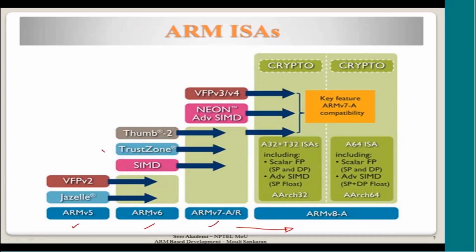Security is very important, especially in networking, and there is all the encryption and key generation, those kinds of things which are required for network protocols. There's a lot of support from the ARM processor with a separate module for it, and then Thumb-2 is an additional add-on to the Thumb state, where not only 16-bit instructions get integrated in the Thumb-2 technology, even a few 32-bit instructions also get integrated, being in Thumb state.